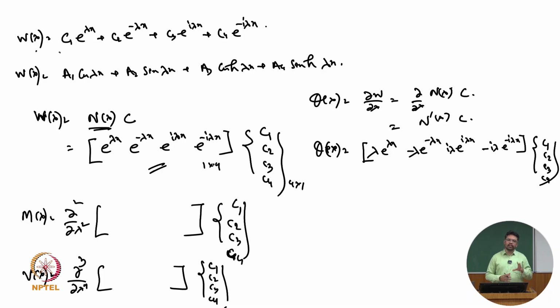You can think of it as very close to the shape function, but there is a small difference. A shape function is usually written as N(x) once it is written in terms of the degrees of freedom. Instead of the unknown C, if you place u1, theta1, u2, theta2 here, then this will be your shape function.